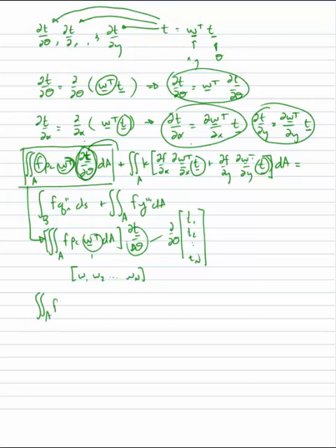So it would be the first element of this times the first element of that, plus the integral over the area of F times rho c times W2 dA multiplied by dT2/dθ, plus, and then finally we get to the last element, so it would be the integral over the area of W sub n times F times rho c dA times dTn/dθ. So this is one equation that involves all these integrals of these weighting functions and then all these derivatives of temperature.